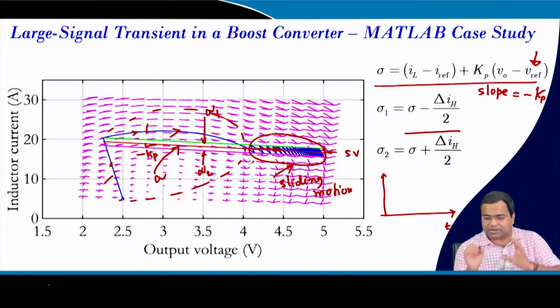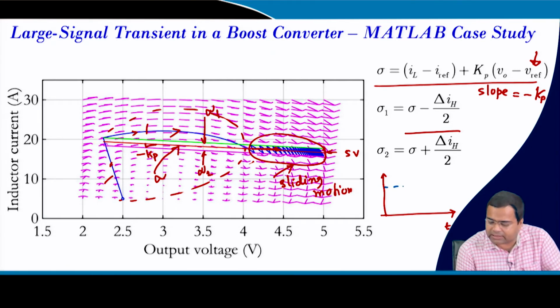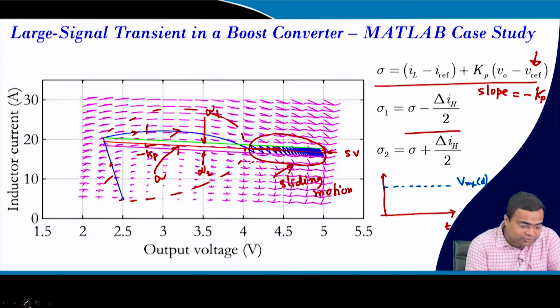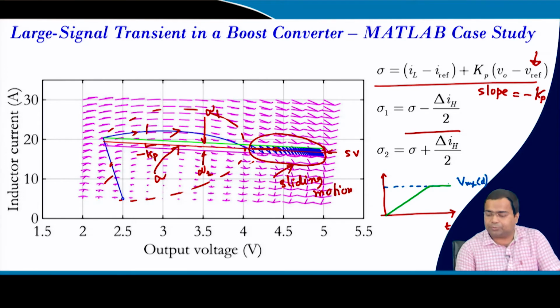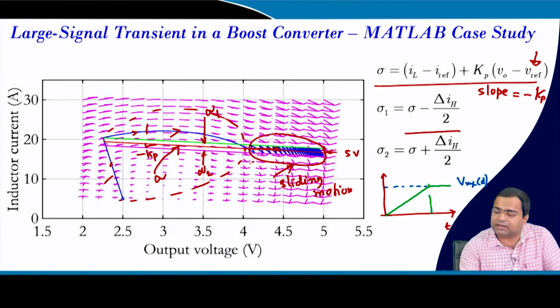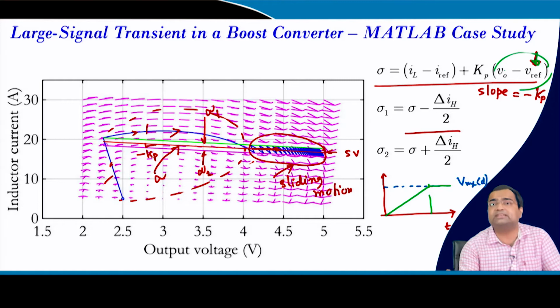So this is our typical desired VREF, but in order to get startup for a boost converter, we should raise the voltage like this and then keep it here. You need to put some kind of slew limit, so that this slowly increases, and the error, because your initial voltage is 0, slowly starts up.